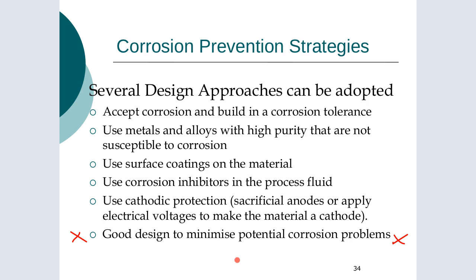So avoid stagnant regions. So when you're putting in designs, if you're draining a tank, for example, we have a tank like this and we have an outlet here. What you want to do is to have a tank more like this, that's U-shaped, and we have the outlet down the bottom, so it's free draining. Okay, so here, not going to cover this. I'm limited in terms of what I can draw. This one here is bad, so we'll get that on X.